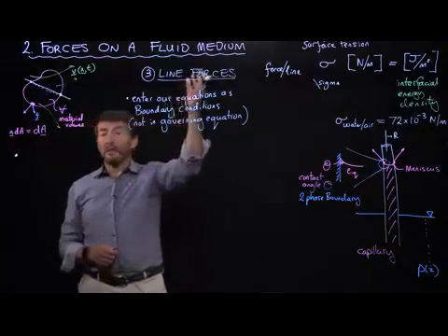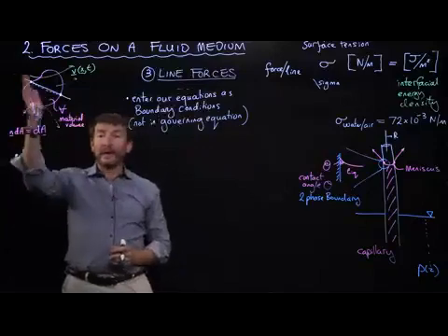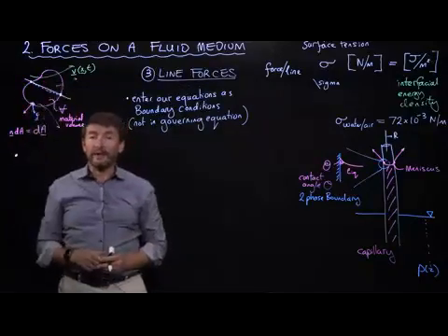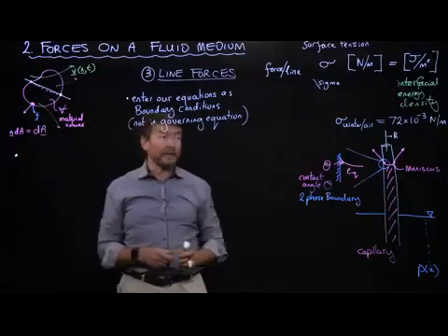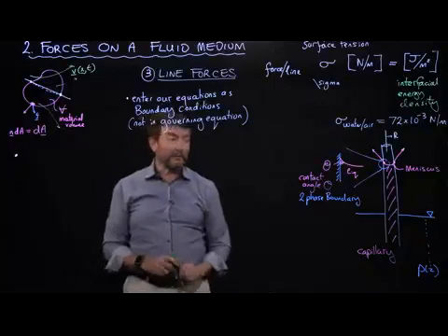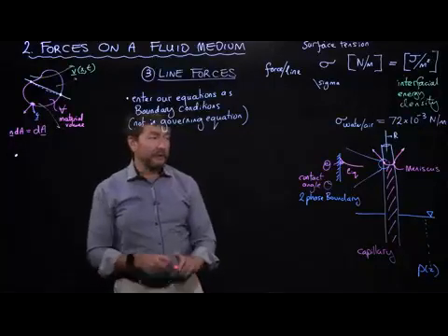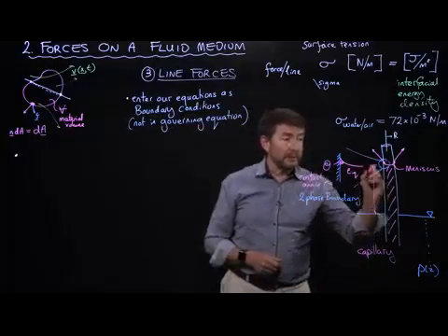And so it now becomes clear why we think about them as line forces, because the magnitude of them is going to depend on the length of the line that intersects with our control volume. We can try and work out exactly how big that is by doing a force balance on this material element. So let's think about the forces that are acting on this material element. Let's denote the height of this by h.